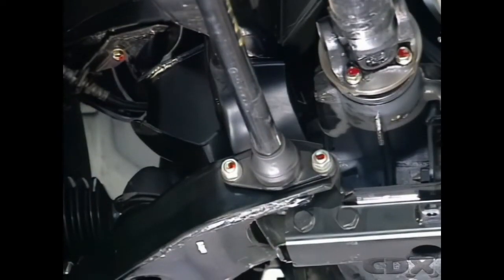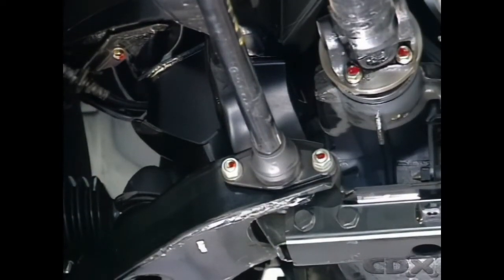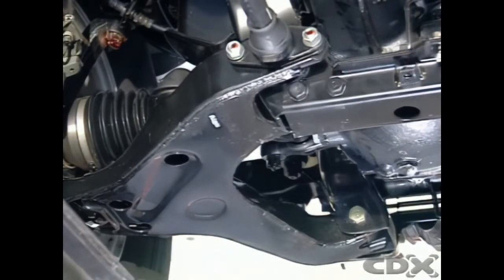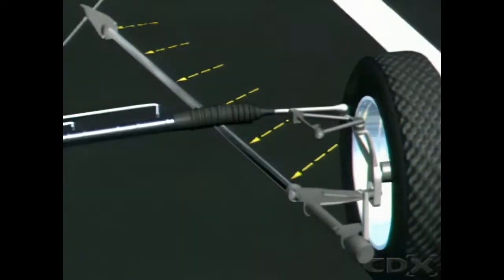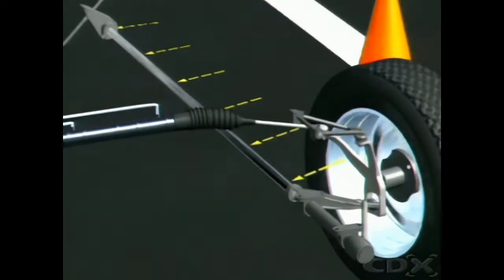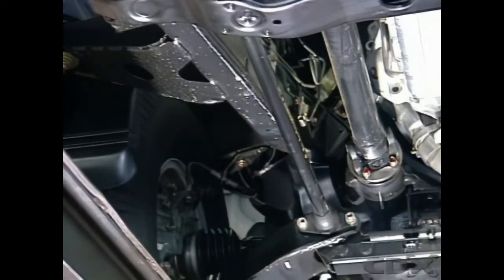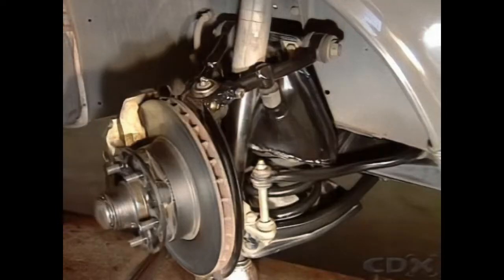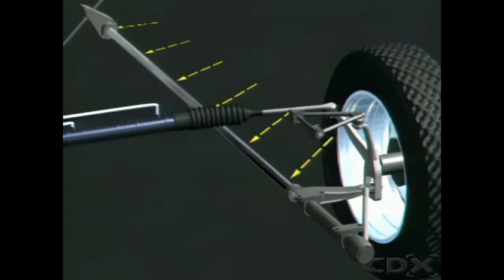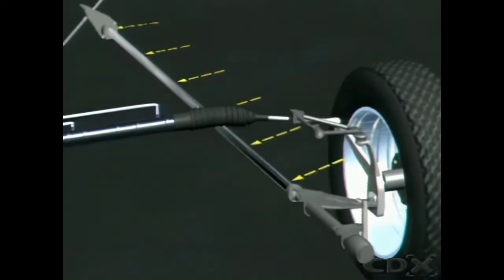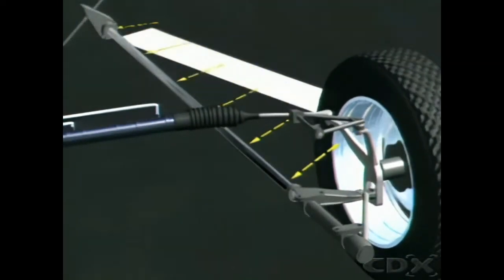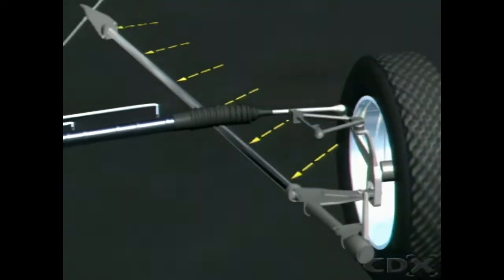The torsion bar is attached at the inner fulcrum point of the wishbone or control arm. As the suspension is deflected, it twists around its centre. It can be fitted to the upper or the lower link, depending on the type of vehicle. The upper link is shorter than the lower one, irrespective of the springing method used. When the suspension is deflected, the unequal lengths allow the track of the vehicle to be maintained near constant, but with some changes to camber angle.